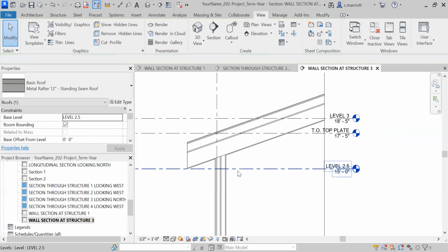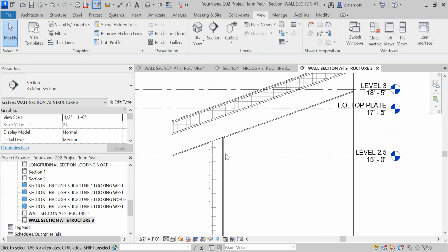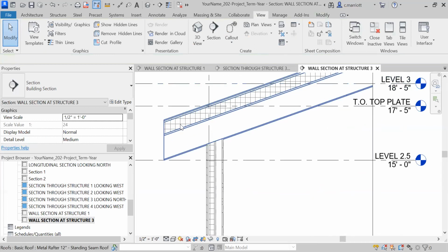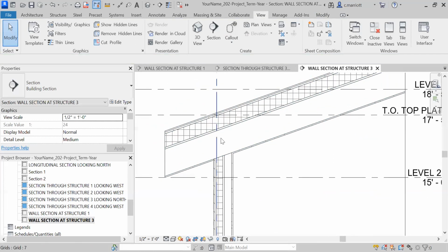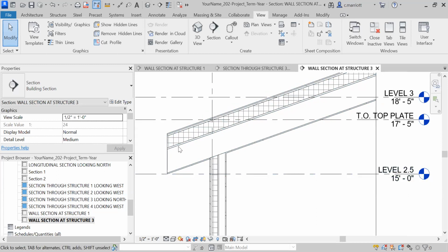All right. Now, one thing that we'll be working on is the insulation. You can see here the way that the wall assembly and the roof assembly work. These insulation layers are not joined. So if we were to actually detail it like this, we have a huge gap where heat and cold would be passing through the assembly. So we're going to need to bring this up. We'll also be adding some detail at the fascia and adding some of the components that make up the framing.